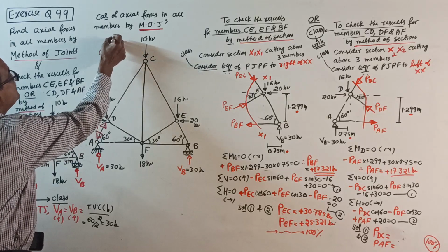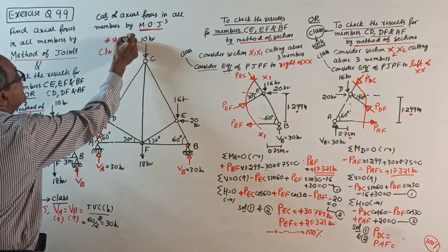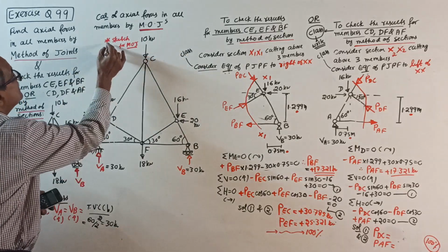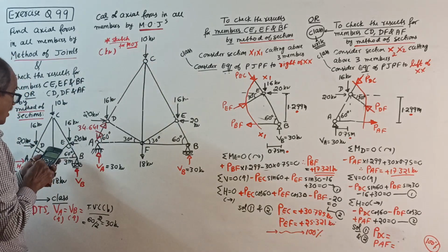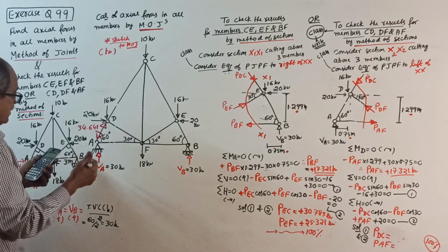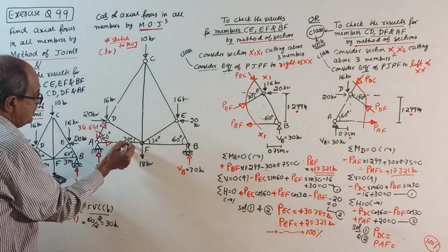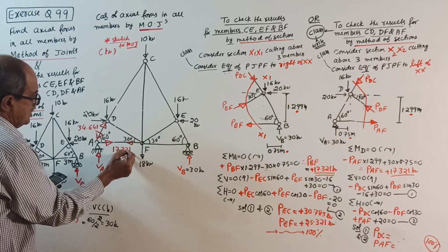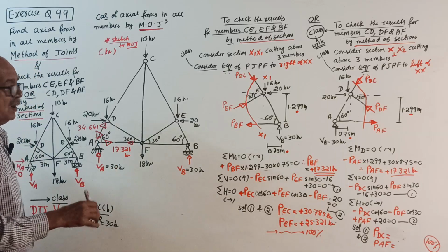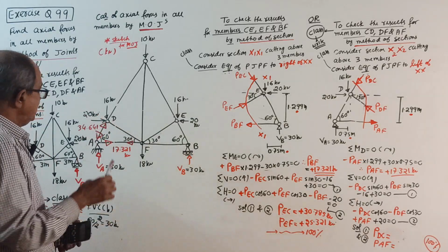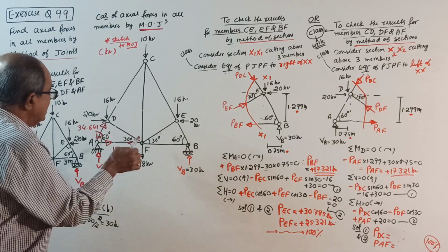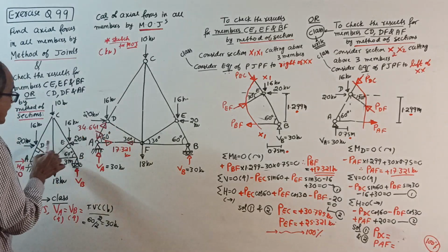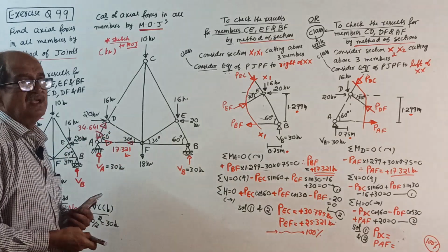This is the star sketch. Remember, star sketch for method of joint. I told earlier. Okay, then into cos 60. 17.321 kilonewton. Okay. Then now I will come to the joint. See, if this is 60 degrees, this is 30 degrees because this is a right angle triangle, 90 degrees here, question given. So I explained this one.